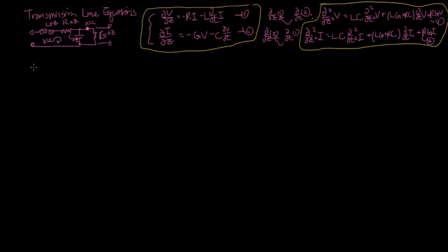So let's start with our inputs. We're going to look primarily at the voltage. So remember we did a slight variation on the forward-backward propagating wave, where before we were just talking about it as general functions of, in the case of forward propagating waves, t minus z over vp, and backward propagating wave would be t plus z over vp. In this case, we're specifying that they're sinusoids. So that would be an amplitude cosine of omega t minus z over vp, plus a wave going in the negative z direction, which will be V0 cosine of omega t plus z over vp.